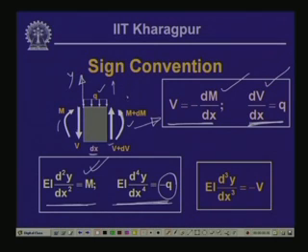So, any loading directed upward is positive, and since this q is pointing downwards, q is negative, and rightly we have EI d4y/dx4 equal to minus q. Also we have EI d3y/dx3 as minus V with the positive shear pointing upward. So, these are the expressions which we use for evaluating the equation of the deflection curve y.